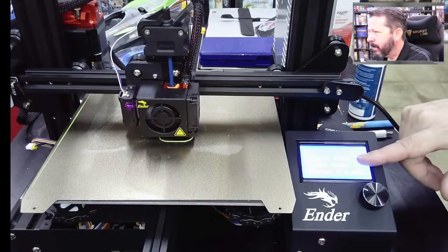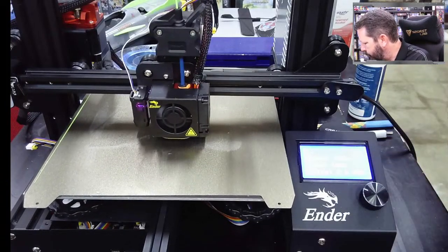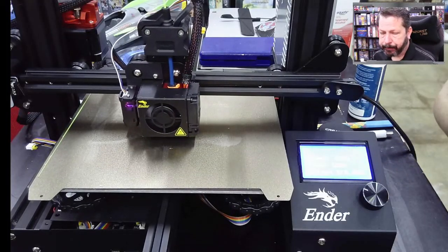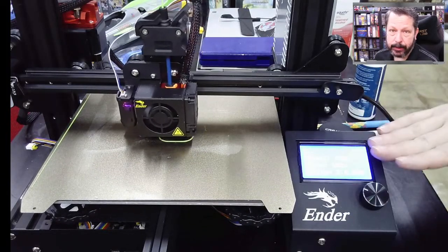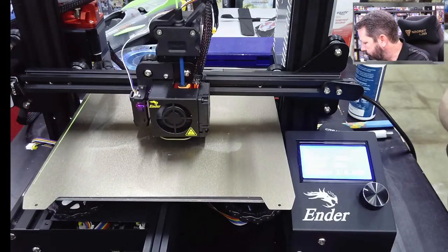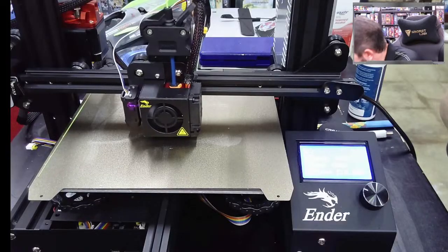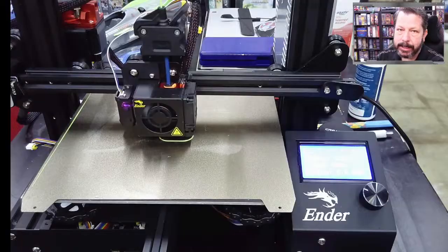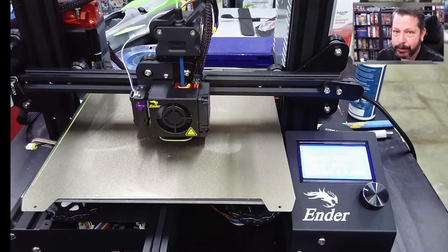This one, in this menu here, I can change the speed, so how fast it's printing. I could even change the flow separate from the speed. So maybe it looks like it's over or under extruding. I can change the flow rate while it's printing to adjust for that. Since we're getting close on time, and it has printed, I probably wouldn't want to change any of these during a calibration print because you're trying to measure the baseline.